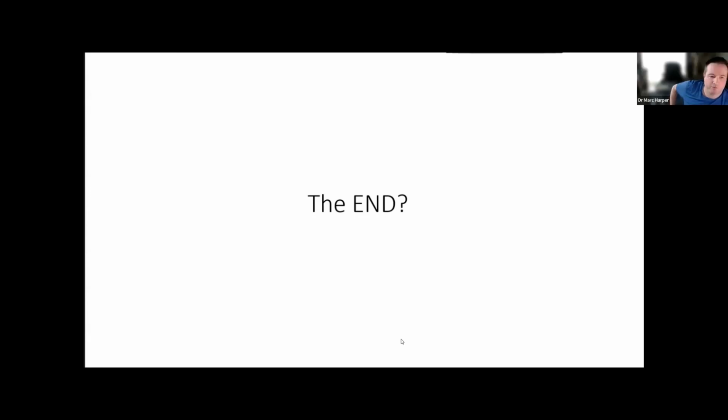So, yeah, it wouldn't be a shirt. We wouldn't do a shirt pocket. That's called a body. So the body SAR test I was referring to, which is the 0 millimeter test, would be the equivalent of a shirt pocket. The SAR there has to pass that very strict limit of 1.6.